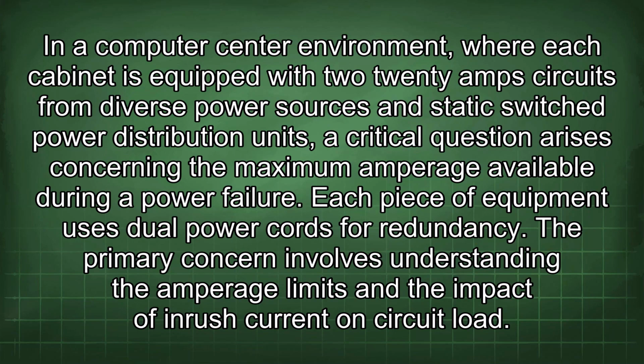In a computer center environment, where each cabinet is equipped with two 20-amp circuits from diverse power sources and static switched power distribution units, a critical question arises concerning the maximum amperage available during a power failure. Each piece of equipment uses dual power cords for redundancy. The primary concern involves understanding the amperage limits and the impact of inrush current on circuit load.